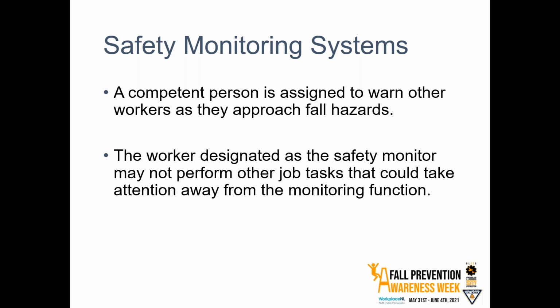With the next steepest roof up, which is 6 on 12 to 9 on 12, you have to use 2 things instead of 3, so we're adding an extra bit of safety. And then with the most dangerous, the highest pitch, which is the 9 on 12s to 12 on 12s, I suppose a 12 on 12 couldn't really exist, that would be just a vertical structure. But the most stringent rules have to be used, and it's very specific in our regulations what's required for roofing in that category. I think I did one job once where I had to get up on a roof somewhere in the 9 on 12 range, and didn't like it. I gotta say, that's just a little too steep for me, especially with the winds that we have here in our province in various areas.